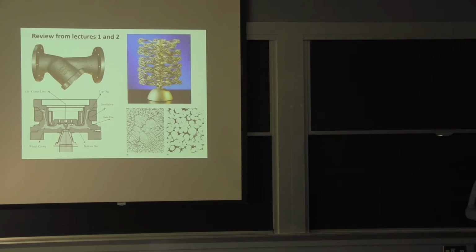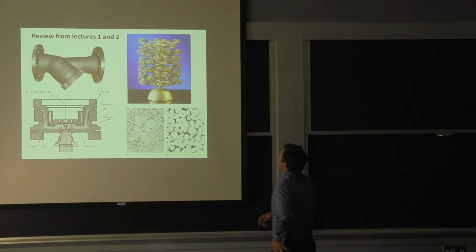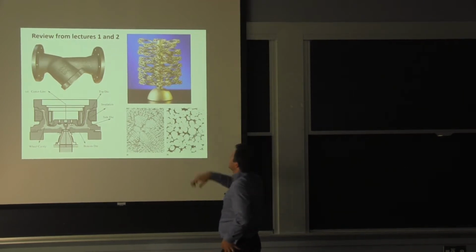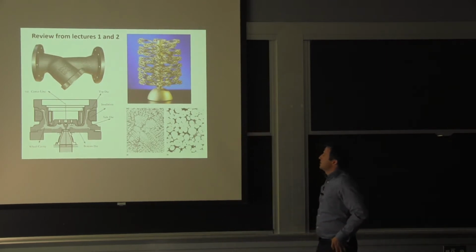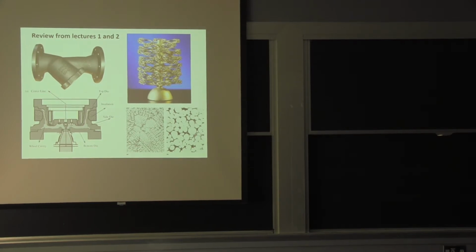Now there are a lot of systems there in terms of risers, making sure that you have a little extra room for the liquid, so any contaminated liquid is not part of the critical component that you're trying to make. It just gets accumulated in another piece. Like this whole tree going up, these are jewelry items, and the whole tree going up and even on top is not something that we're interested in terms of parts. So it's going to be scrap metal that's going to be reused, either for casting after it gets purified again.